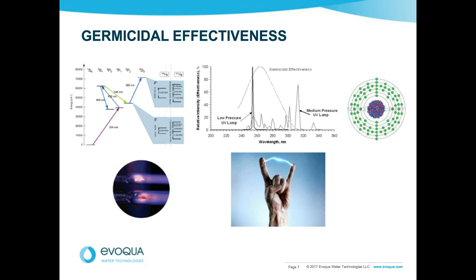From a medium pressure lamp, you tend to get about 8,000 hours. So I would limit lamp life to 15,000 hours for a low pressure lamp, and I'd limit it to 8,000 hours for a medium pressure lamp. Try and avoid a very aggressive start and stop cycle, because that will shorten lamp life. Try and reduce the number of starts and stops per day. Up to 8 start-stops a day is fine. The lamps can cope well with that. But avoid starting and stopping them 6 or 7 times an hour, because that certainly will shorten lamp life.